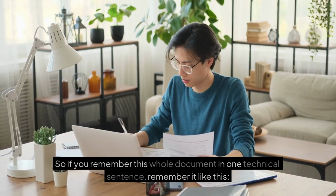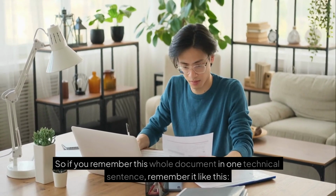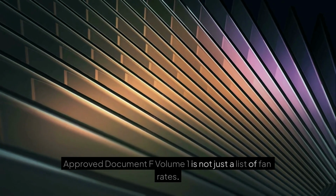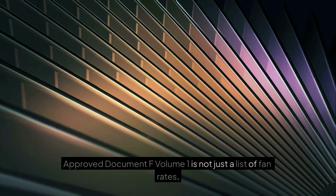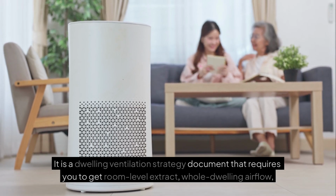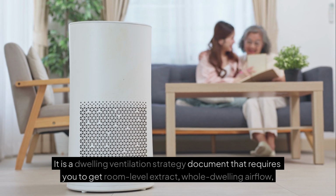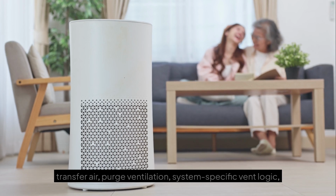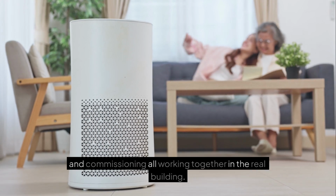So if you remember this whole document in one technical sentence, remember it like this. Approved Document F Volume 1 is not just a list of fan rates. It is a dwelling ventilation strategy document that requires you to get room-level extract, whole dwelling airflow, transfer air, purge ventilation, system-specific vent logic, and commissioning all working together in the real building.